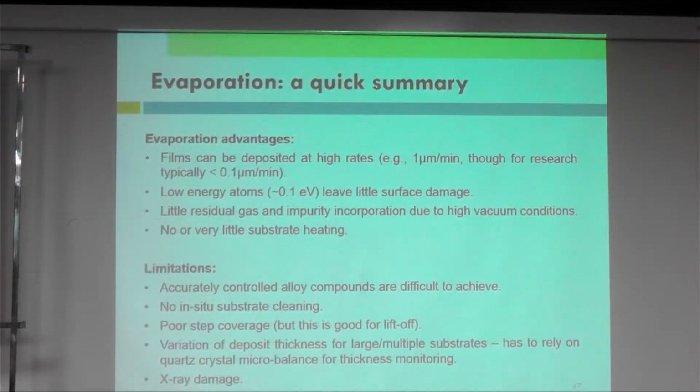So in summary, for evaporation, film can be deposited at high rates, for example 1 micrometer per minute, though for research typically 0.1 micron per minute. The low energy atoms leave little surface damage, there is no bombardment of atoms, little residual gas and impurity incorporation due to the high vacuum conditions, and no or very little substrate heating.